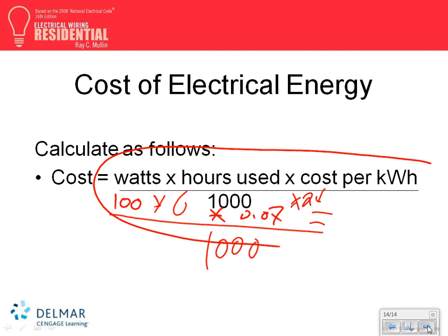And if it's in the second building, what do you need to do too? It's already bonded there. So here's another pair. Now if the impedance is the same, the current will be divided by 3. The current is now divided between 3 pairs. So under what circumstances is that allowable? Only existing buildings, and if you prove to the authority having jurisdiction that there is no metallic path in between them.